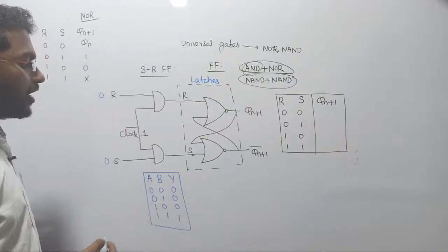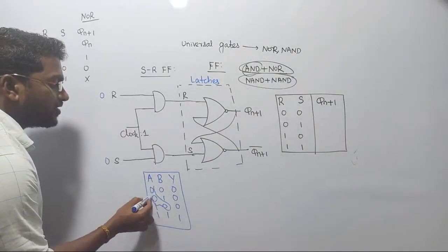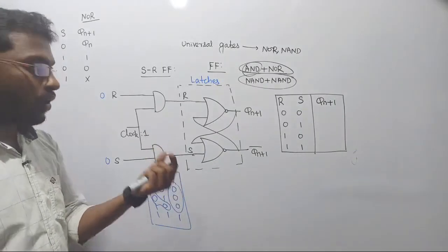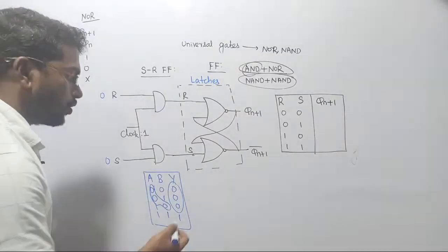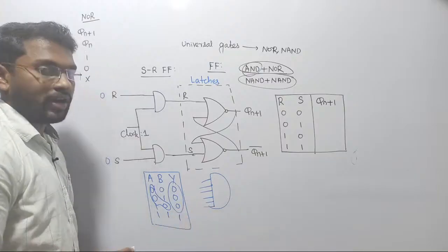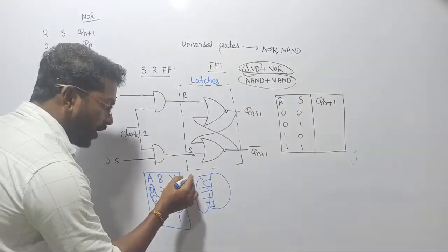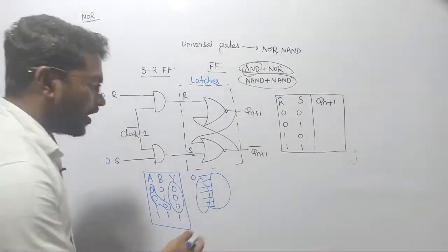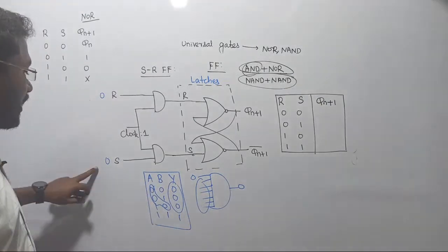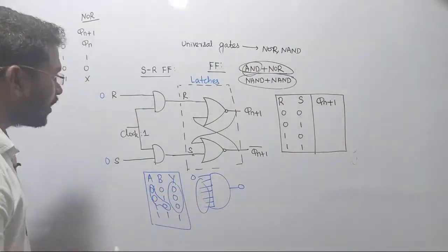If you realize the AND gate carefully, if I find at least one input as 0, automatically the output is going to be 0. It means you can consider 1000 input lines, and if I find these 1000 input lines are not known, but there is only one input line connected with 0, automatically the output of the AND gate is going to be 0 only. So the conclusion is, if I have 0, then I can guess the output of the AND gate.